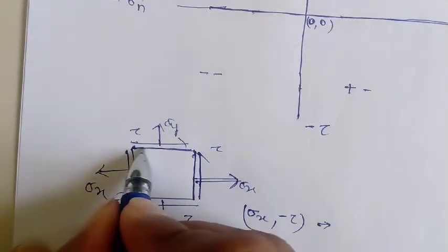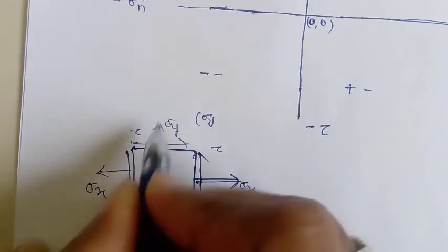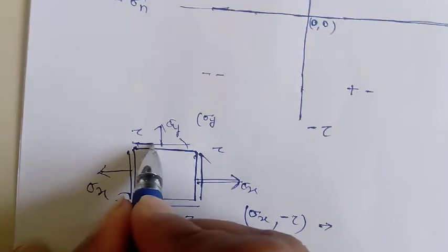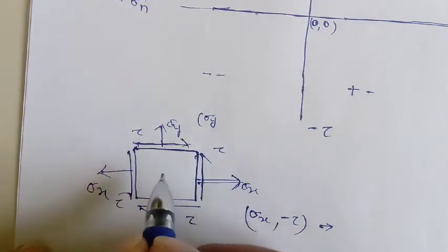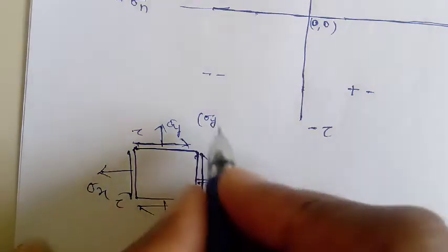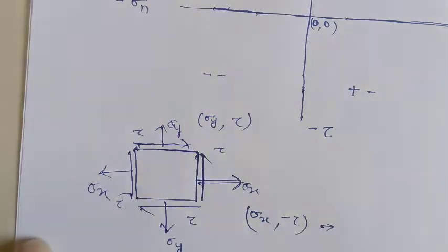Now in the y plane, this sigma y is positive because it's tensile in nature, and the shear stress rotates this element clockwise, so here this will be positive.